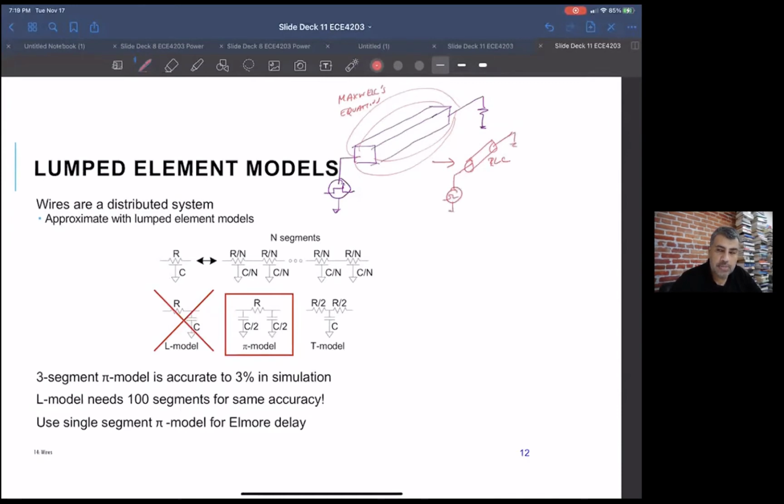And then typically in a circuit class, so far, you've been thinking of it as a lumped model, having an R and a C, okay? But in reality, in chip design, you're somewhere in between these. This lumped model of just thinking of a line, of course, depends on how long the line is and the values for the R's and C's.